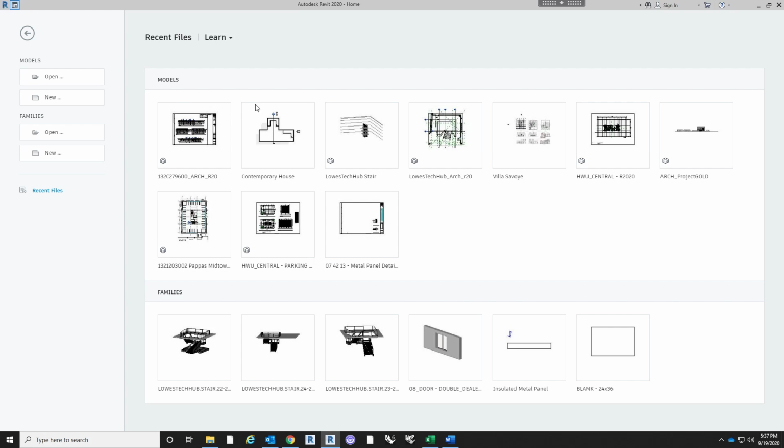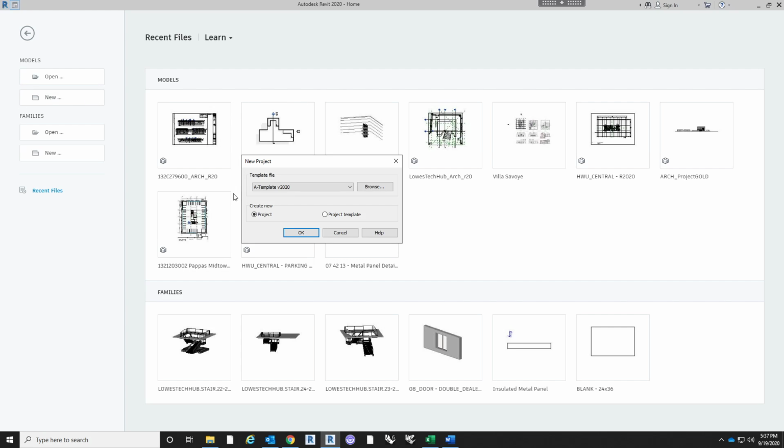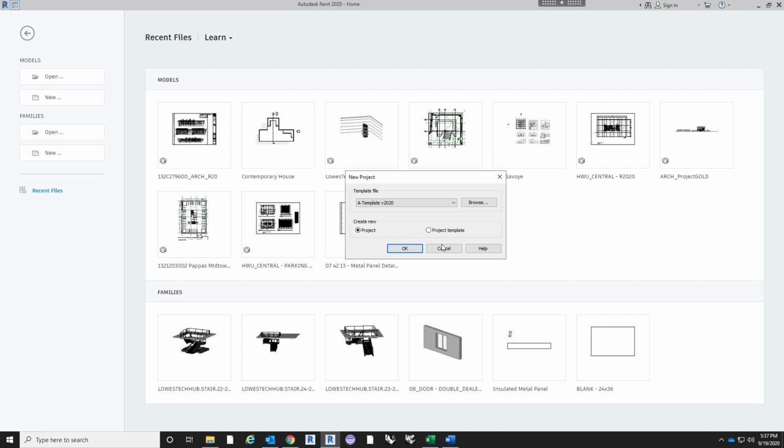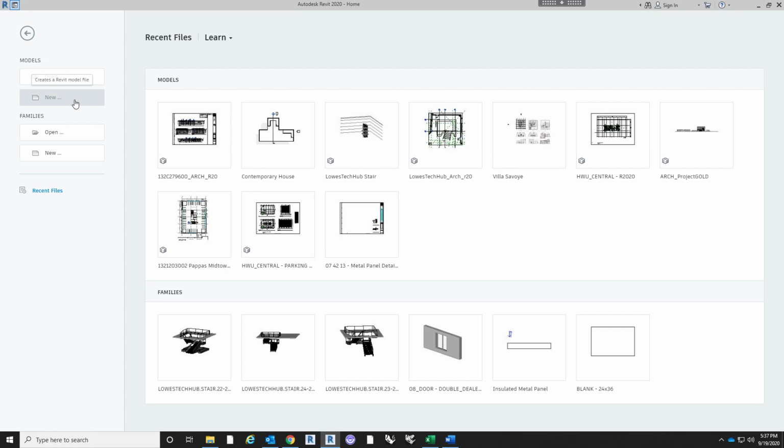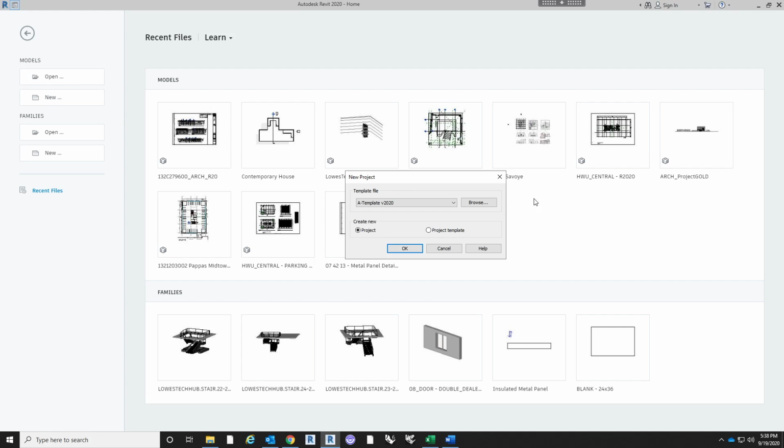So to get started, let's just do what we have always been doing. A couple of you have run into this mistake by accidentally opening your Revit template instead of creating a new project with the Revit template. So please be aware of hitting new first, okay? Do not open the actual Revit template, because then you'll be changing the template, which you don't want to change because it's a template. It's your starting point. So make sure you're creating a new project from the Revit template, okay?